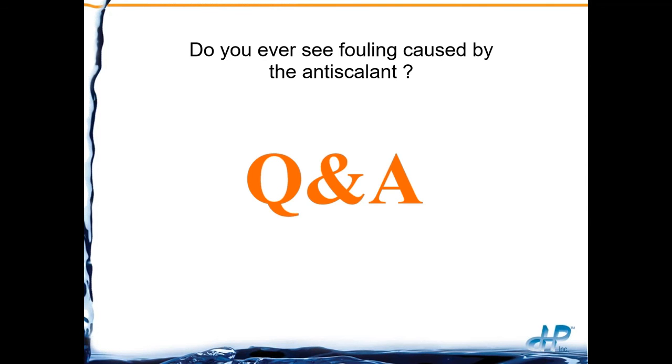We have run into, I should say, in the last couple of years, a case where the scale inhibitor pump malfunctioned, or I should say the check valves in there did, while the unit was shut down, and it started siphoning scale inhibitor from the day tank directly into the RO system. Since it was straight scale inhibitor, which can be a real sticky polymer, it laid out and did plug up the membrane. That's very uncommon to see.